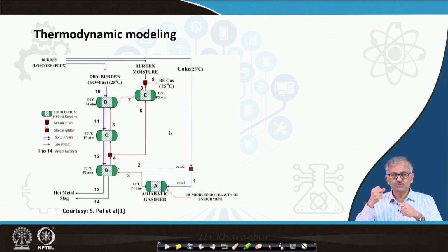A part of the gas will move along with some amount of heat as well as some amount of CO, which will not interact with the solid because it doesn't have sufficient time for interaction. So we can bypass a certain fraction of the gas to the upper reactor without participating in the reaction, as a measure of deviation from equilibrium.